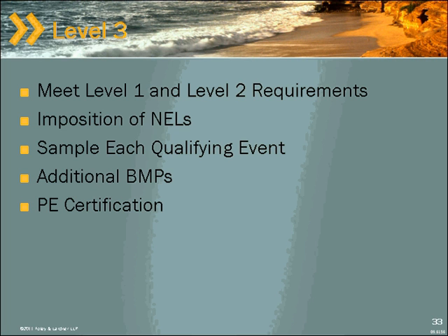For the level 3, which we're surmising here probably will not stick, if it did, however, you'd be expected to meet the level 1 and 2 requirements. This is what would blow you into the NELs, at which point you'd be obligated to sample each and every qualifying storm event, not just 2 storm events per year, but each one, implement additional BMPs, and of course all of this needs to be certified by a PE. So again, this is likely not going to stick, but this is what it would have been, perhaps.